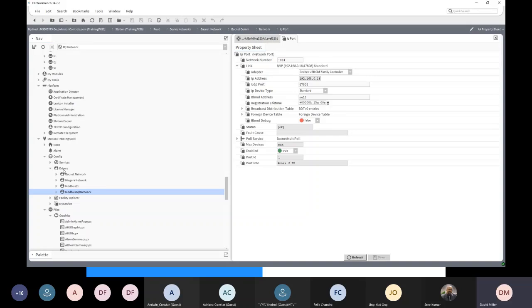And the point count matters, because if you connect to a Daikin VRF, you'll have a single BACnet IP connection to the Daikin VRF, but every indoor unit that you map to is possibly going to bring in 10, 20 points, just say 10 points. If there's 100 indoor units, there's 1,000 points there.